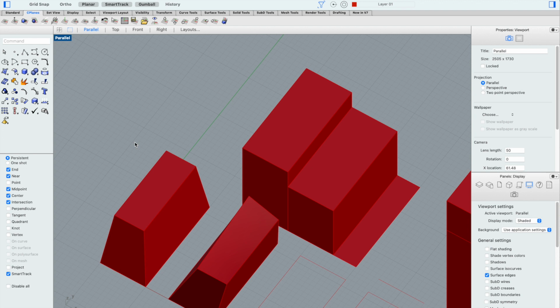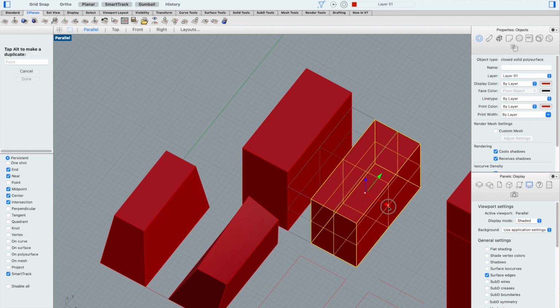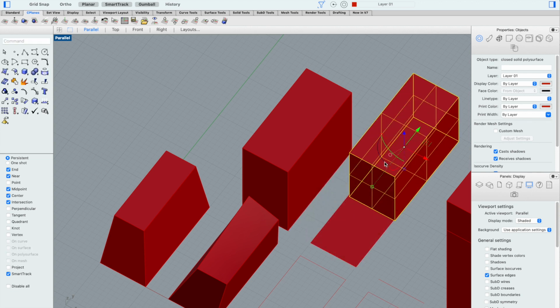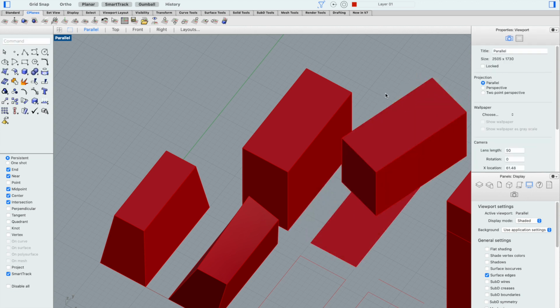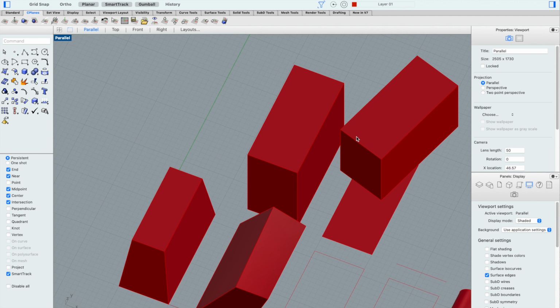So move plus rotate is a useful duo of commands, but there's one that has that built into it, and we talked about it a little bit in the 2D version of this tutorial, which is Orient. So if I take this guy, I move it, and I put it somewhere a little bit less convenient, right? Now I can combine those steps into one step and use the Orient command just like I did with the curve in the earlier tutorial.